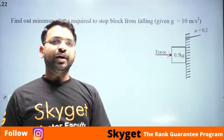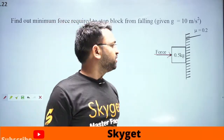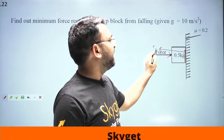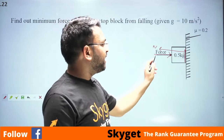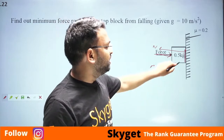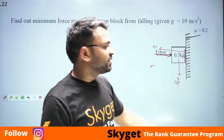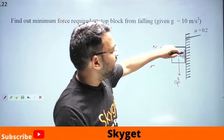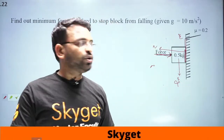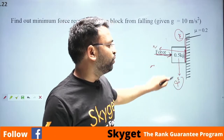If you remember the free body diagram that we have done in our video sessions, since there is contact maintained, the normal force will be acting over here. So in the x direction, the force is balanced by the normal, but in the y direction, there is a mass, and because of that mass there is gravity acting downward, and opposite to the gravity there must be friction which is mu into N. In order to stop this, this value has to be equal to mg.